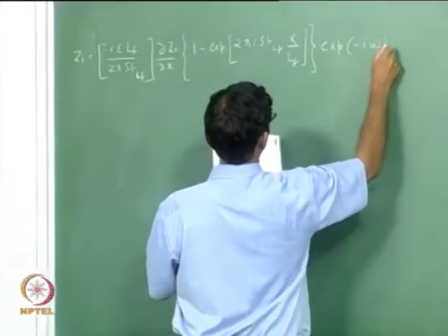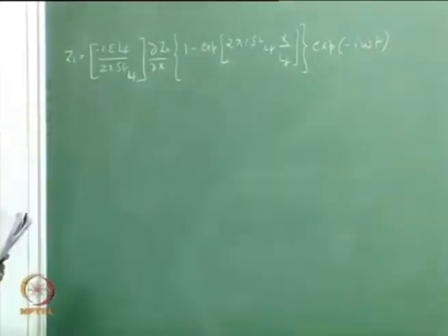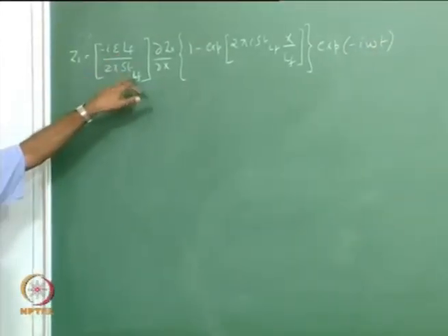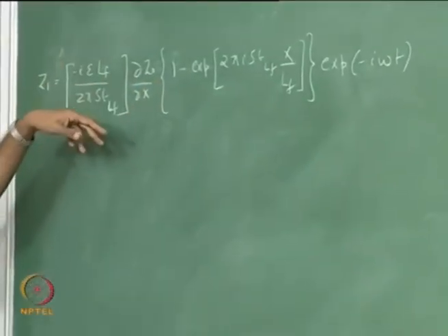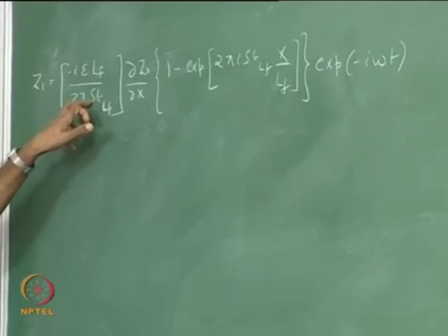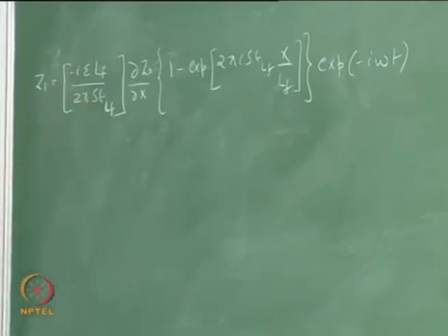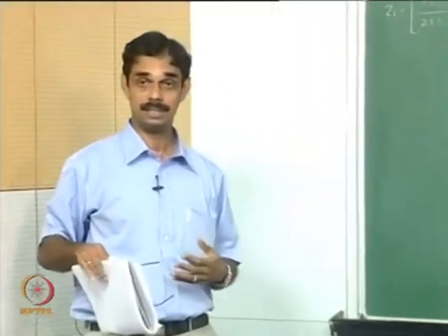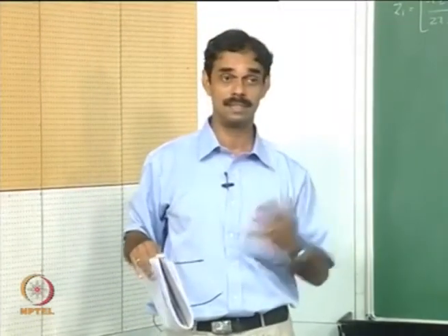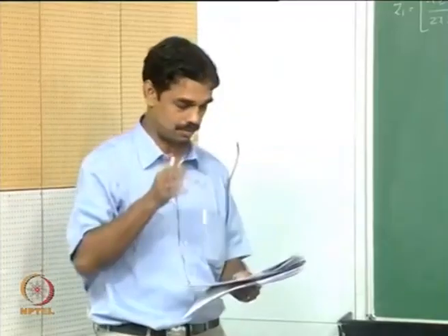You can redo the Strouhal number, write it in terms of LF by multiplying top and bottom by LF, and then you can write a Strouhal number in terms of the flame length. Many people prefer to do that because flame length is something which we can measure very easily, and when a flame is oscillating you can see the flame length oscillating.